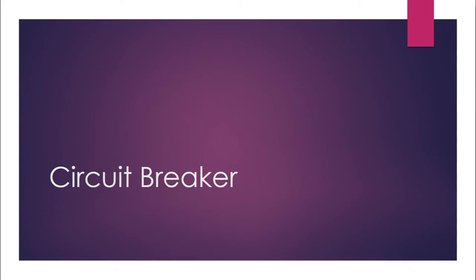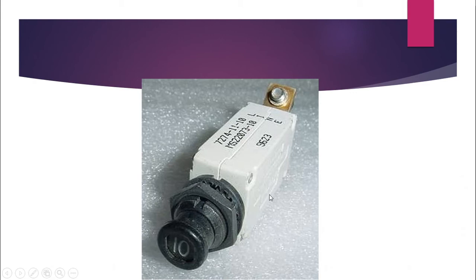Now, to help keep the electrical system of an airplane safe, we have these devices called circuit breakers. A circuit breaker is a little device that is hooked into the electrical circuit, and it pops or breaks the circuit if too much current is passing through the breaker.